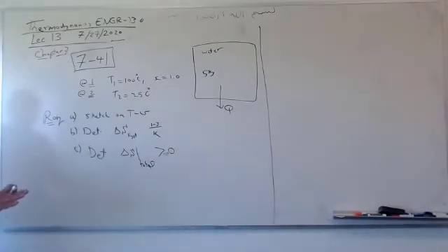But it can be 0 if you have both adiabatic and reversible, like, for example, turbine, compressor, pump, where there is no heat. But boiler, no, boiler has heat. Evaporator, condenser. If you have heat transfer, delta S must be greater than 0. So this process, rigid tank, I took heat, cooled it down. What is the most important thing here, guys? This is a rigid tank. What do you learn from this?